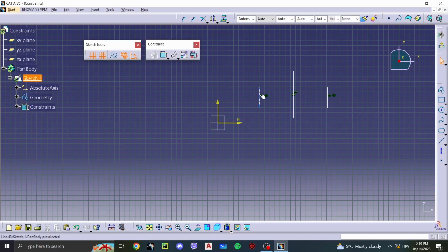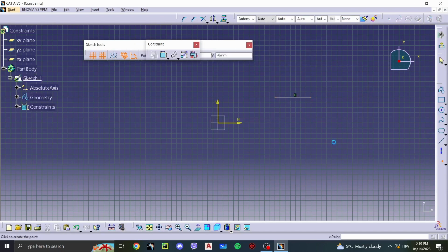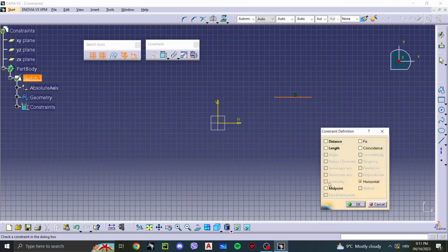Next up is midpoint, a fairly simple one. You draw a line and a point somewhere in the line. This would be the midpoint of the line. Let's say we want it to be this. So when we select the line and the point, then our command, we get the midpoint. What it does is extend the line so this point becomes the midpoint of the line.